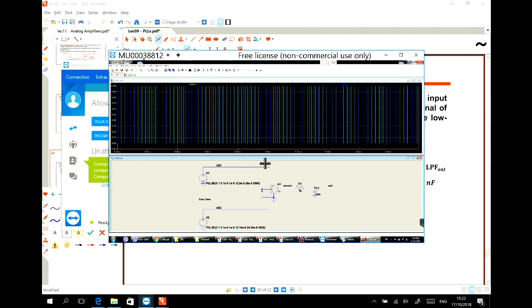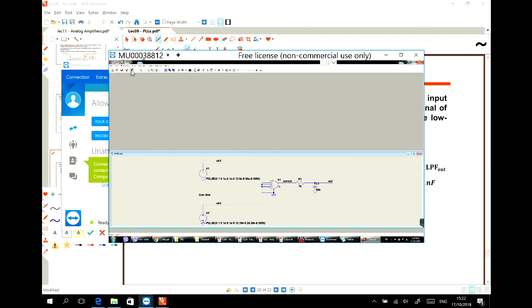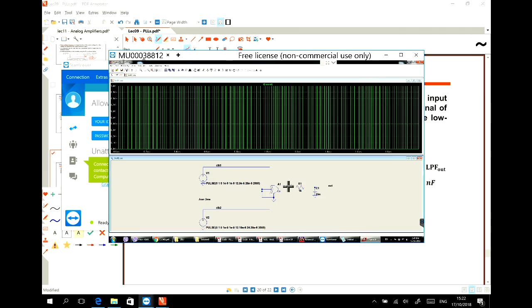So the output of the XOR is like this. You see that, for example, in the first cycle, the overlap between these two is small, and then it gets higher, higher, higher, and then again, when the phase shift is around pi, then again it drops. The duty cycle of the XOR out. And then our output will be a kind of triangular shape.